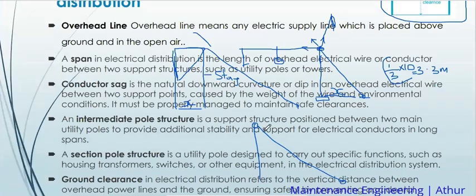Okay, even the outrigger bracket that would have come here, the stay would have been like here after putting this bracket. Even this distance is not there. And the pole is here. So what we do, if it is like a road, we put what we call a flying stay. And the flying stay just moves across the road up, and then you go and put another pole on the other side of the road.